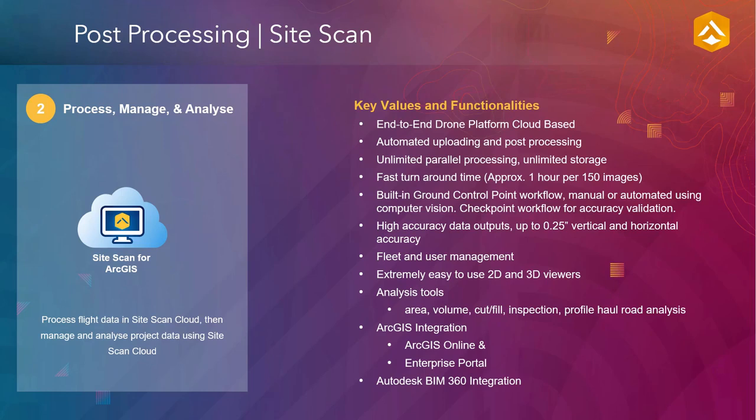Once completed, the imagery can be analysed in SiteScan in both 2D and 3D. We can get elevation models, contours, we can do volumetric analysis, cut and fill, measurements, and pavement analysis. And then we can push out to the enterprise, or we can download for further offline processing.